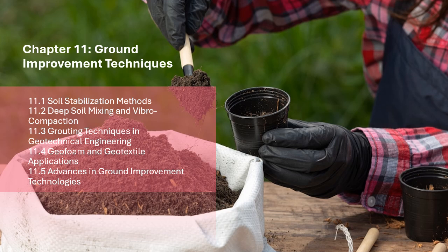5. Landfill lining and covering. Geotextiles are commonly used in landfill construction to separate waste from the surrounding soil, prevent contamination, and facilitate the drainage of leachate.